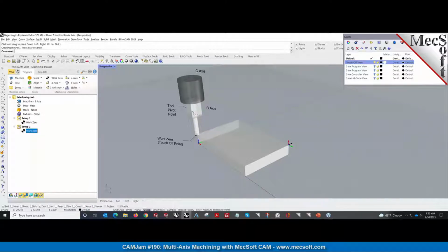So this is a tool pivot point. This is what Don mentioned in a slide. So we have a 5-axis machine configuration shown schematically here. We have a C-axis. That's basically the C-axis rotates about this. The Z-axis here, the blue line. I'm not sure if you can see it. And then the secondary axis is the B-axis, which rotates about the Y-axis here. And this is the point where the tool is actually pivoting. So as the B-axis rotates, the tool is pivoting about that point.